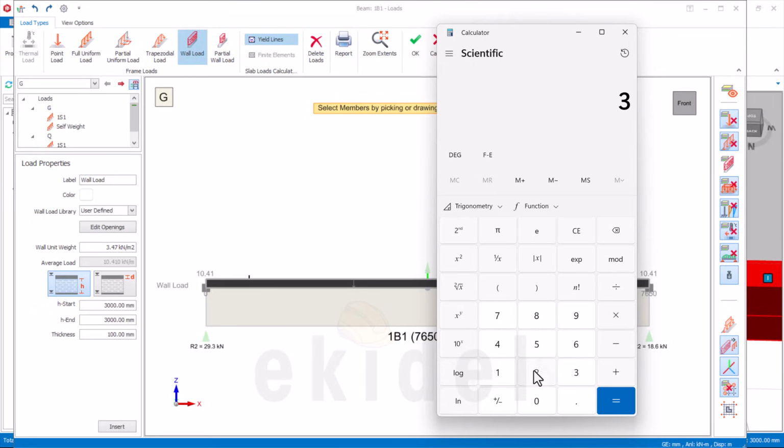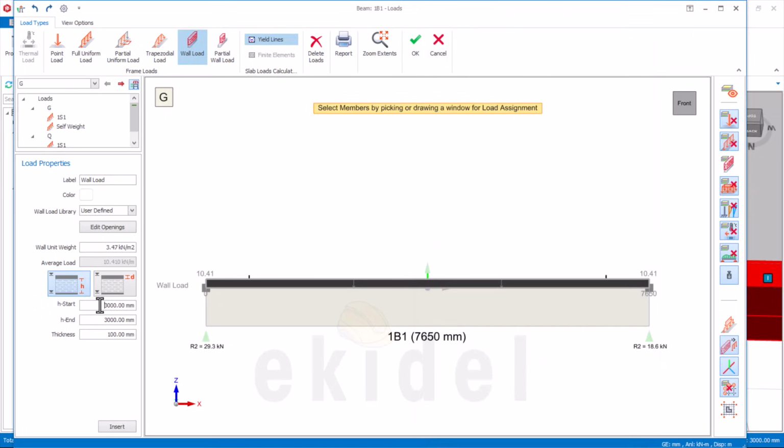This one becomes our beam depth, and this is our headroom. So this is now 2550. This is the portion of the height of the story that the block will occupy. So we have 2550, and here 225 as the thickness of the block wall.